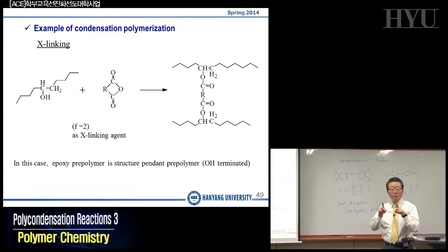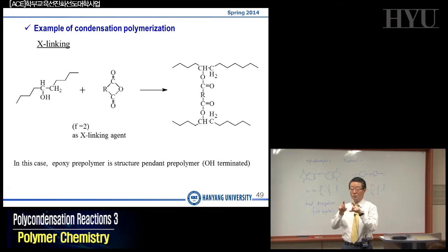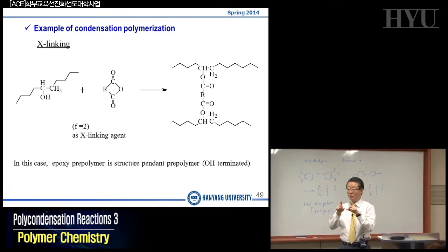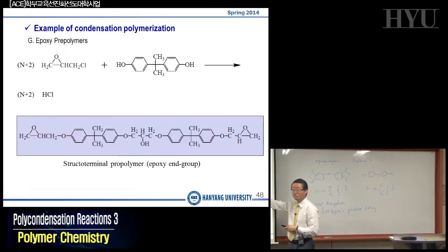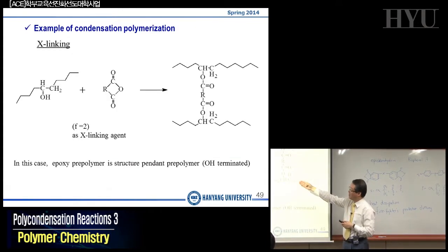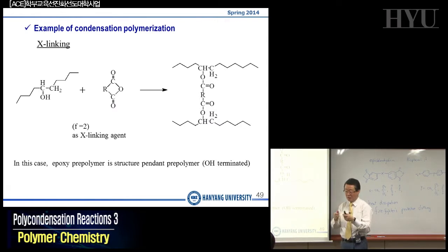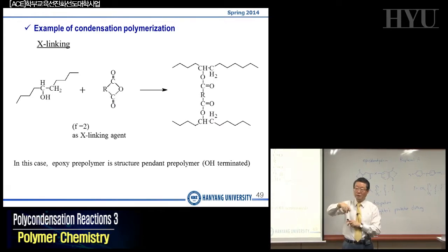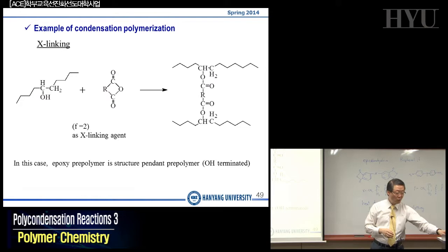But you have two tubes generally if you want to apply this epoxy adhesive. The first one contains this linear polymer. First tube contains the linear polymer, and second tube contains the cross-linking agent. So that first component, linear polymer, and the cross-linking agent are mixed together. Okay, mixed together, and apply that mixture to the two broken parts.